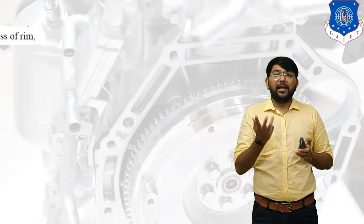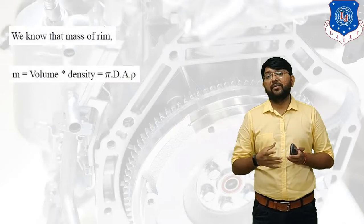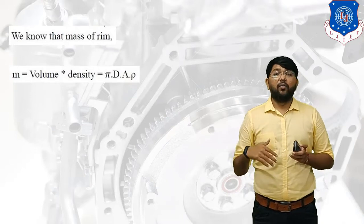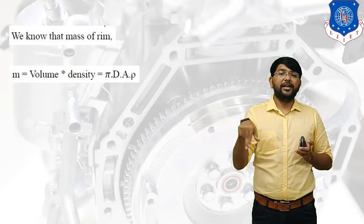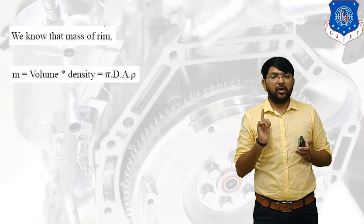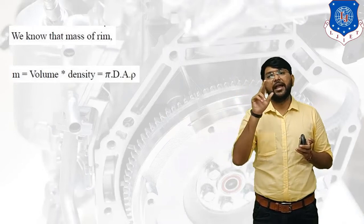Clear? Okay. Now we know the mass of the ring. What is the mass of the ring? It is the multiplication of volume and density. Now what is the equation of volume? If we multiply the cross sectional area of the flywheel rim by its perimeter, we get the volume. So cross sectional area is capital A and the perimeter of the flywheel is pi into d.